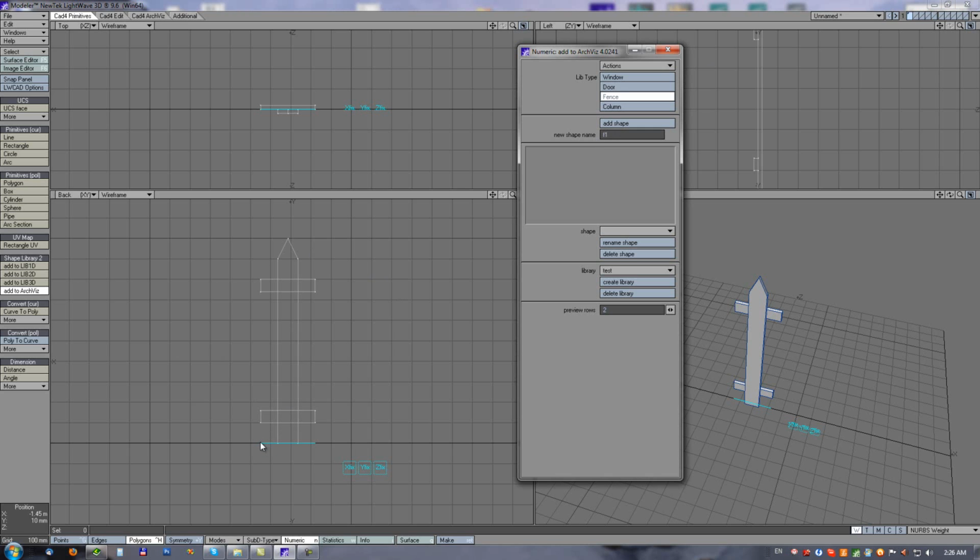a placement line is automatically created, which defines the position of the ground and the position of the left and right connections to other pieces. So with this default line there will be no gaps between fence presets, and it will lie on the ground. So I will add this version.